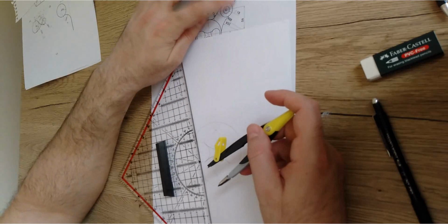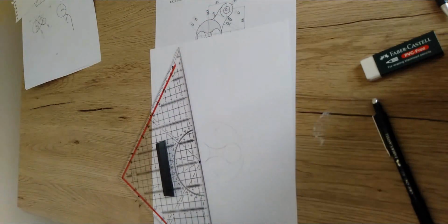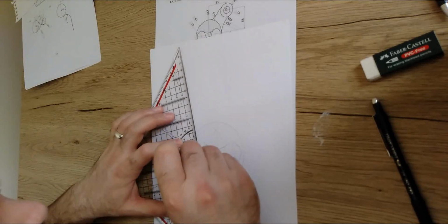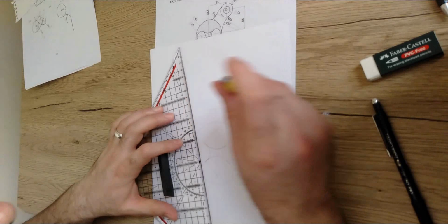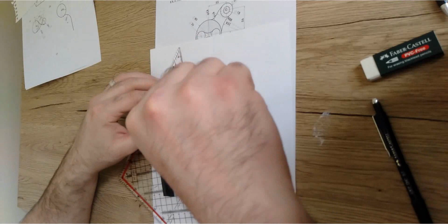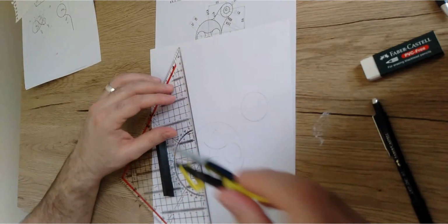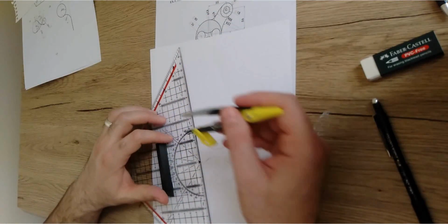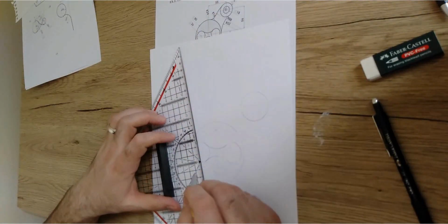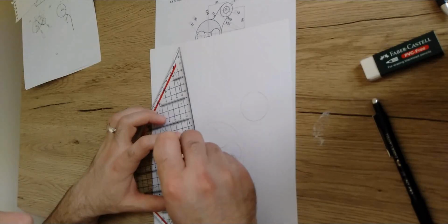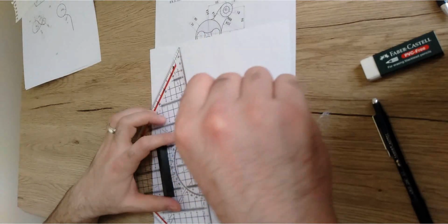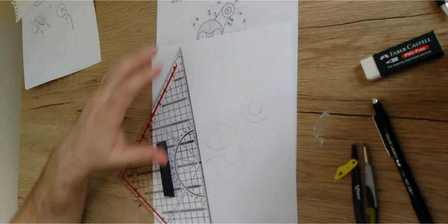The first circle is the base one. It has a diameter of 36, so the radius should be 15 plus 3, 18. It should be 18. So I'm just going to open the canvas by 18. Then I'm going to draw the first big circle, which is this one. Make sense? So this is the big circle here. How about the second circle, the small one, which is basically just a circle, it has no tangencies, but it is a circle with a diameter of 18. It means that the radius should be 9. This should be the small circle. Alright, so I got these two circles.